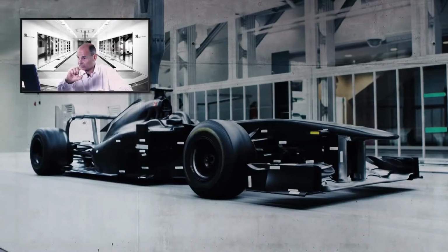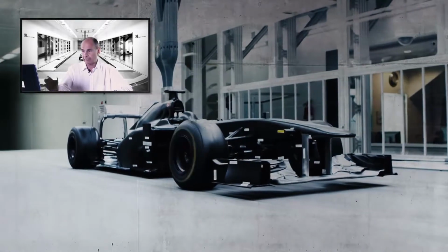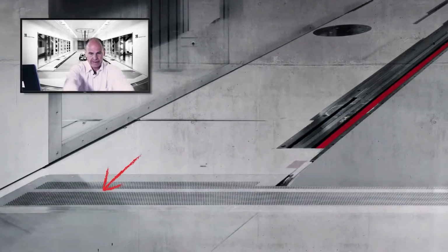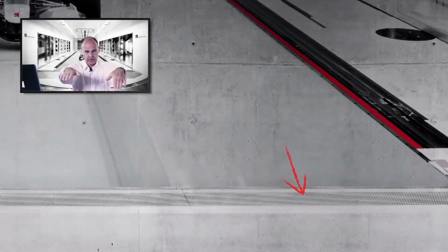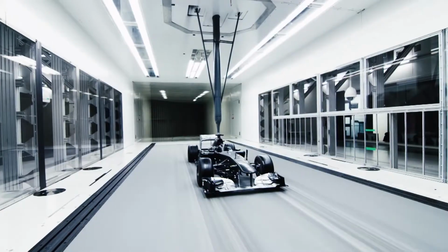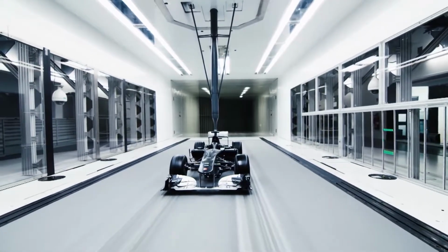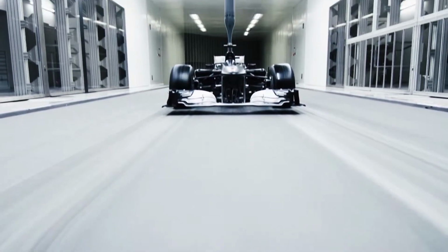And typically speaking, in a decent sized wind tunnel, it's going to be 40–50 millimeters, something of that sort, if your wind tunnel is well designed. You can also just put a patch in front of the working section with holes in it and just suck air through that patch, which will draw air down towards it and speed up the airflow near the surface. Then just behind these systems you put your moving ground plane, which is moved at a speed synchronized to the airspeed, and once you start moving onto your belt, you no longer have growth of the boundary layer.